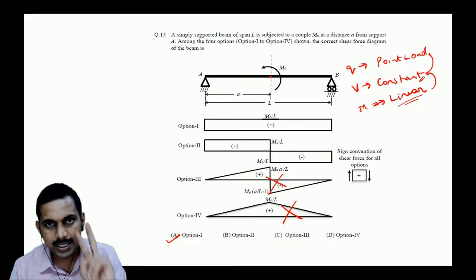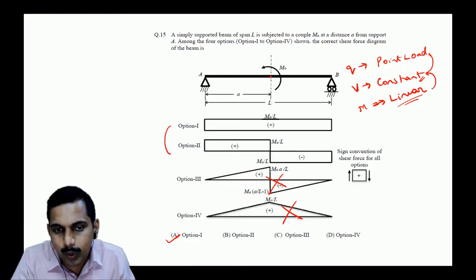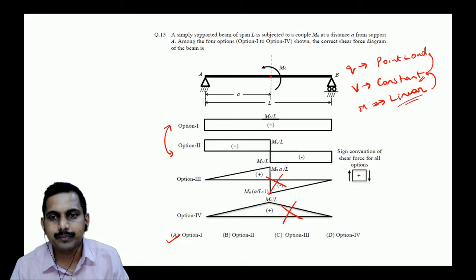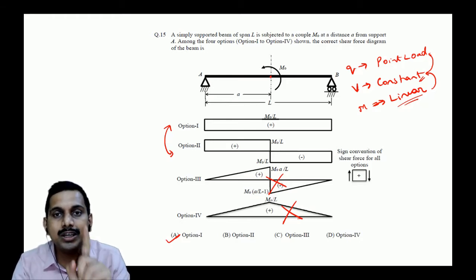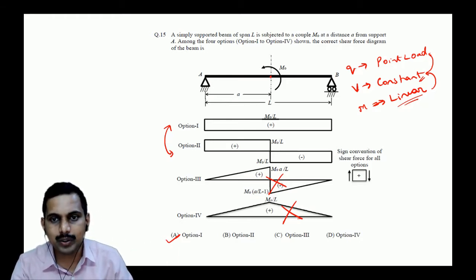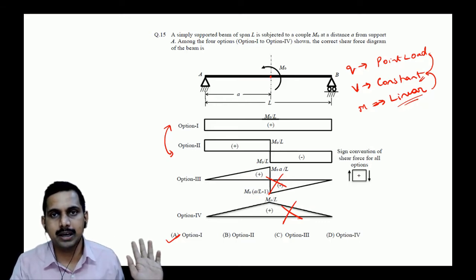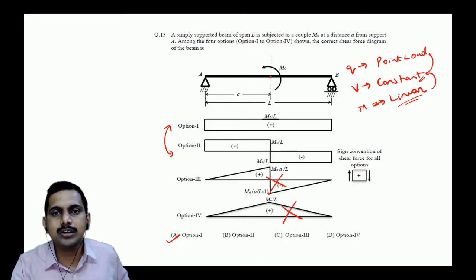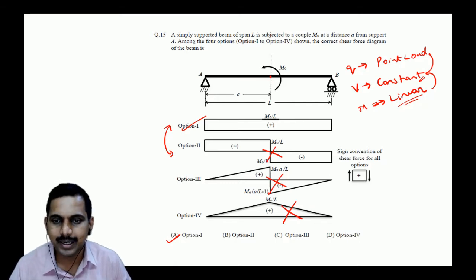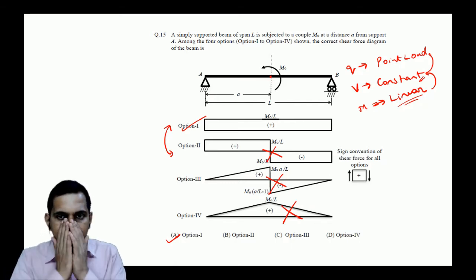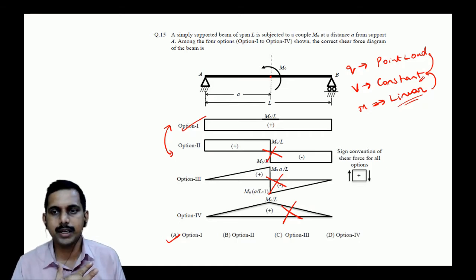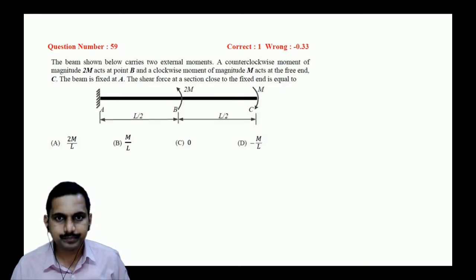It is linear. Okay. Second point, between option 1 and option 2, which is the right answer? Here what is happening is only the bending moment is active. Okay, so when a bending moment load comes, there is no influence on the shear force diagram. Since bending moment does not cause any influence on the shear force diagram, this is wrong, which shows the influence. Only option which is remaining is option 1. Any doubt on this, students? Clear? Fine. Very good. Next one.